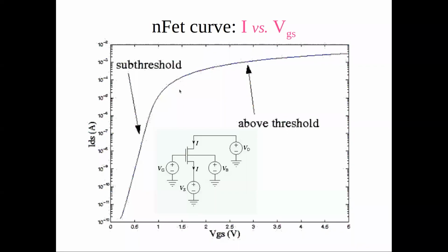Carver Mead was the first to say that transistors are not actually switched off. If I have something that is nanoamps, it's not 0, and I can still use this range in output if I do something fancy that is somehow robust to noise. And this was in the 90s. That's what Carver Mead was saying: let's just try to use this. And because it's close to what real neurons do, let's try to use the same tricks that biology uses to overcome the noise. And so this neuromorphic field comes out of that.